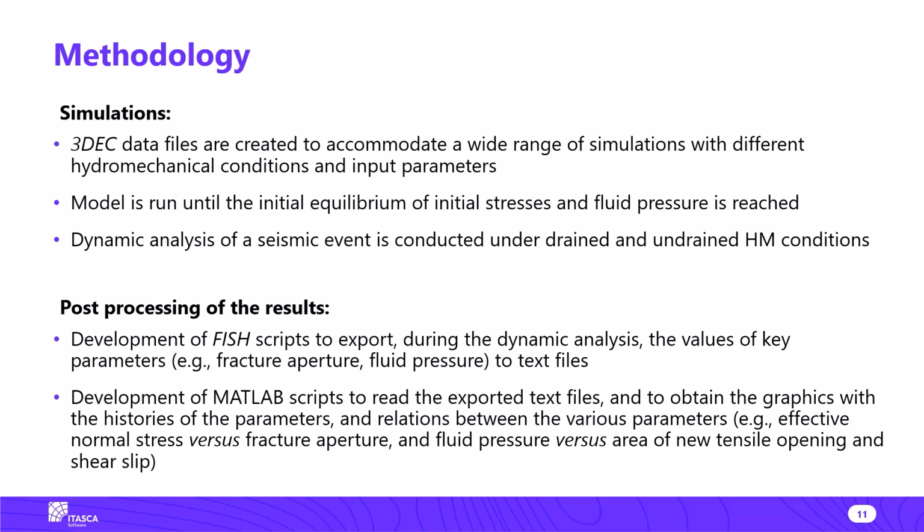Dynamic analysis of the seismic event was conducted, and during the analysis, both drained and undrained conditions were considered. To post-process the results from numerical simulations, FISH scripts were developed to export, during the dynamic analysis, values of key parameters, for example, the fracture aperture and the fluid pressure, and these values were exported to text files. Also, MATLAB scripts were developed to read the exported text files and to represent graphically the histories of the parameters and the relations between the various parameters.